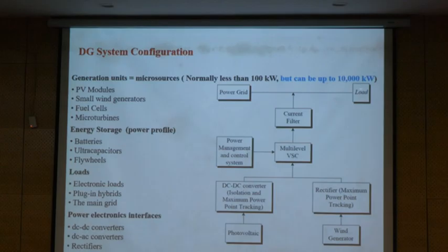So if, for example, the load is nonlinear, you can ask the converter to just provide the active power, but in a smart way you can provide the non-linear part, because the non-linear part cannot be provided by the grid and it can be considered as a disturbance for the grid. So for this case, it is important that we know how to program the converter and somehow compensate or provide a solution for the problem existing in the grid.